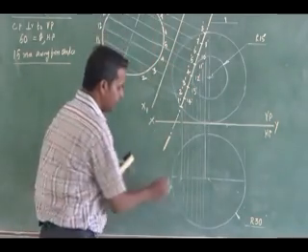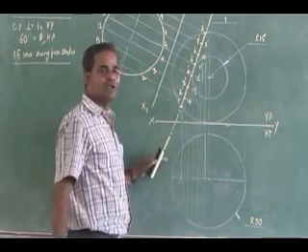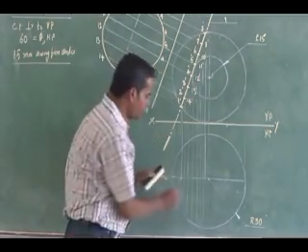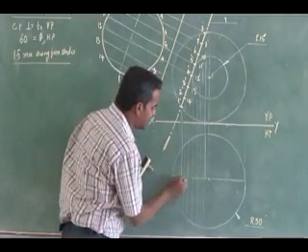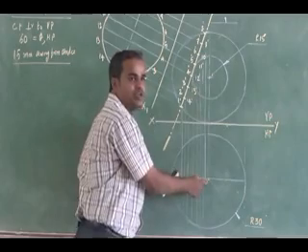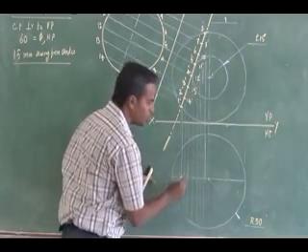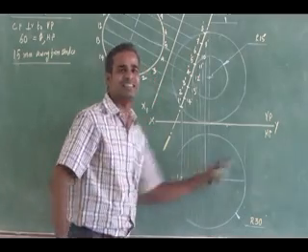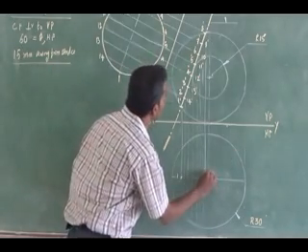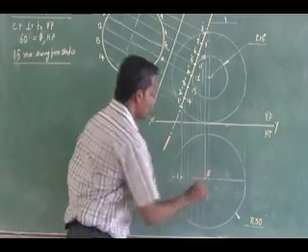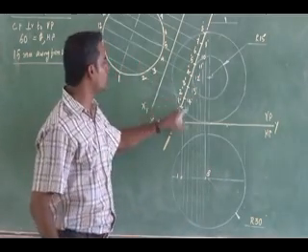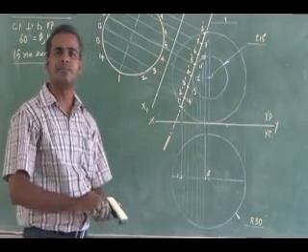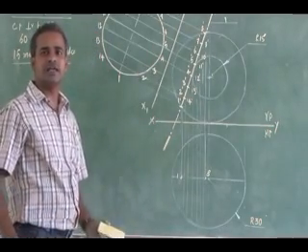See here, I can draw a diametrical line in my top view also. So whatever the extreme cutting points, 1 and 8, they will fall on the diametrical line exactly in the middle. So I have projected up to the diametrical line. So this is going to be my cutting point 1, and wherever this extreme cuts the diametrical line, that is going to be my 8. So what about these intermediate 2, 14, 3, 13? Okay, intermediate cutting points, how can I transfer that? How can I transfer that?